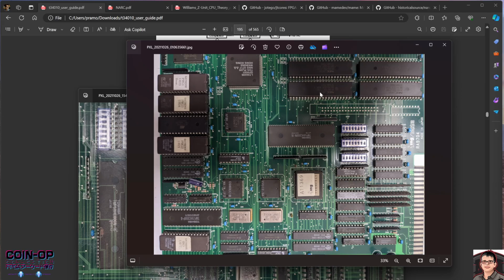You want to work all of that out on the physical source of the board. So that's what I use the physical board for. I take lots of pictures. At the end of the day I want to be able to look at this and understand what each chip is doing and what role it plays. In the case of Rising, there are a lot of custom chips involved, and each of these chips I have traced out and captured data from in order to understand what they're doing. I haven't decapped any of these.